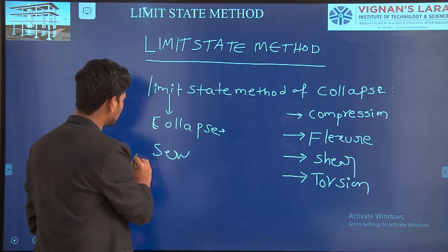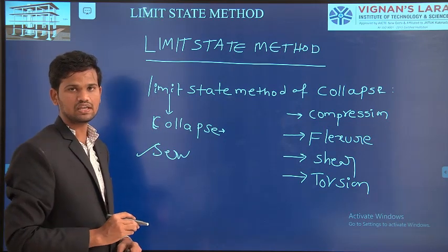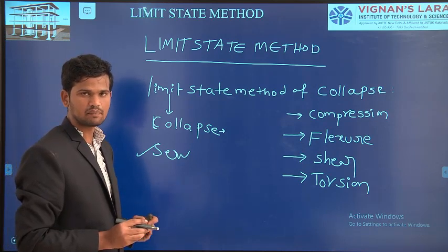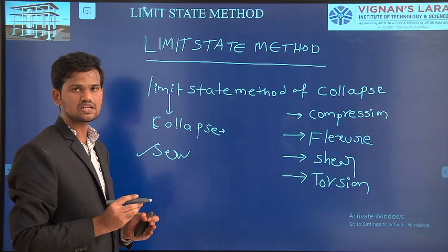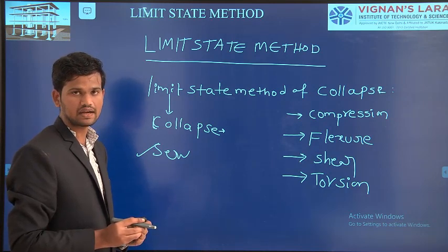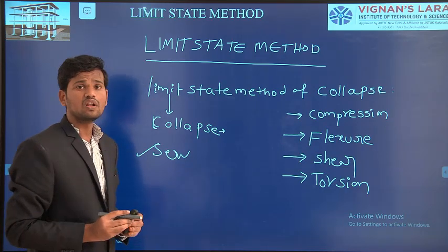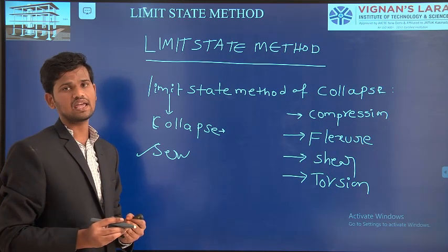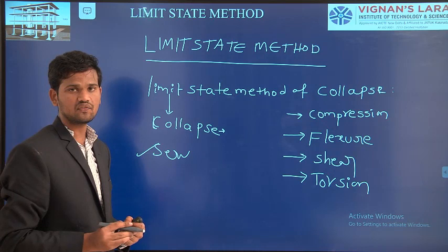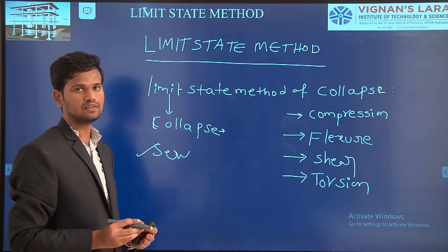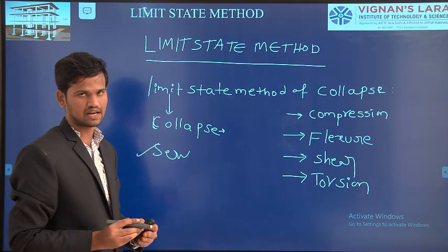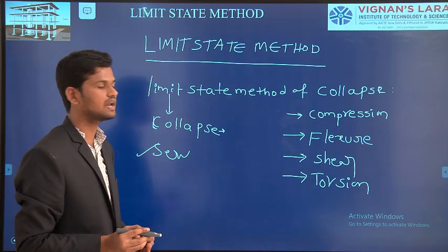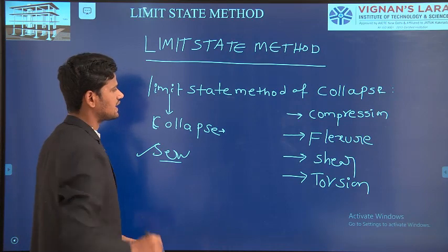Again, in the limit state method of serviceability, we are designing the structural member for cracking, deflection and vibration. That means for however many years you design the structural member, in that design life it should not show any deformation, deflection and cracking throughout its entire life. If you design the structure in such a way, it is called a limit state of serviceability.